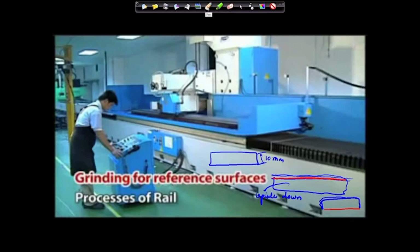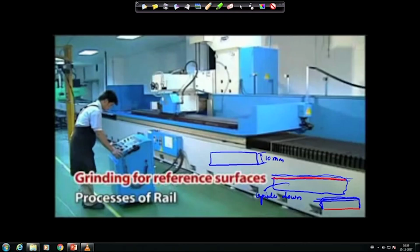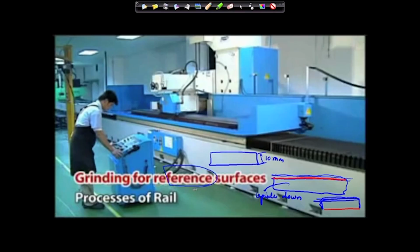Now you apply that 10 millimeter. You measure from here to here how much is the 10 millimeter, and again do one machining operation and one grinding operation so that you get the 10 millimeter. So, when your surface does not have any proper shape, you create one reference surface, and from that reference surface you continue all the operations. That is why it is called the reference surface. The calculation of all the dimensions, be it depth, width or length, will be taken care of by this particular surface reference. So, it is required for this operation also.